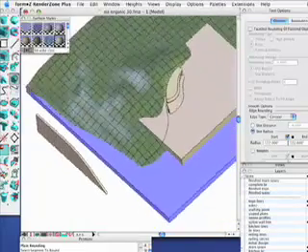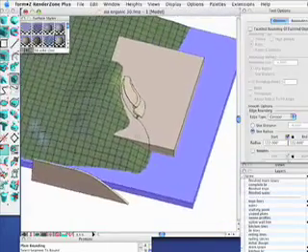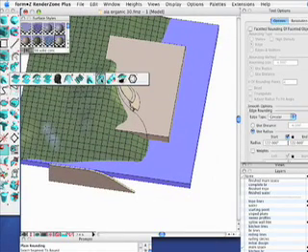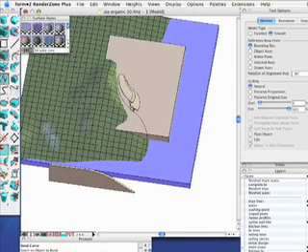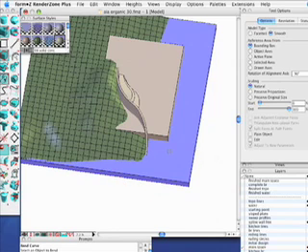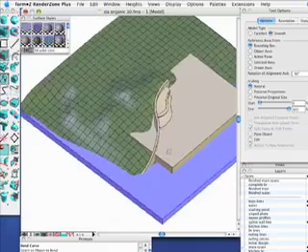So now I'll take my object and I'll turn on this spline I have drawn already, a little S curve, and I'll use a tool called Bend Along Curve. This actually allows you to make an object conform to a path. It's a great way to build a real complex, say a wrought iron stair railing. You could build it flat on a plane and have it conform to the railing of a spiral staircase, for example.